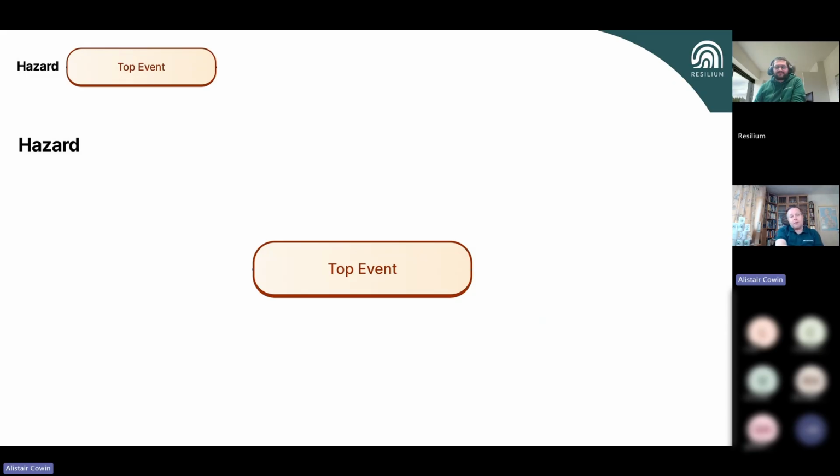If you work in a top tier site, it's typically around release of something bad, something dangerous that you need to manage. So you need to be able to demonstrate that I understand why I have the risk, the hazard, the danger associated with it. And when I'm thinking about the loss of control, I understand where my bad day starts. I don't go to the end, the explosion. They're still important to understand, but I really want to understand this.